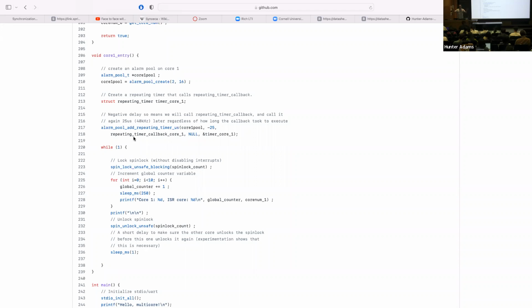If you want the threads that are running on the 2 cores to communicate with one another, there are strategies for doing that. You can use spin locks. And in particular, Bruce has added some multi-core capability to the proto-threads API that allows, for example, for sharing of information between cores using the FIFO that sits between processors 0 and 1.